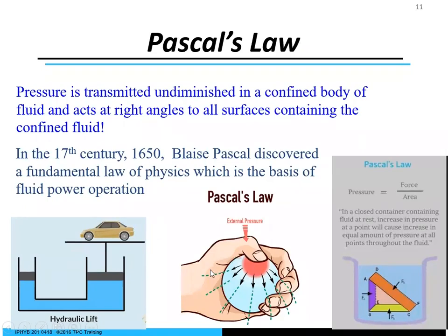Well, what does that mean? That means if I've got fluid in the system, I'm going to push down into a container. It doesn't matter whether that container is contoured or a cylinder. It's going to push that pressure throughout that container. That's exactly what that means. And so Blaise Pascal's law is a fundamental law of physics, which is the basis of fluid power operation. And here's a formula that we need to be very familiar with. So pressure equals force divided by area.